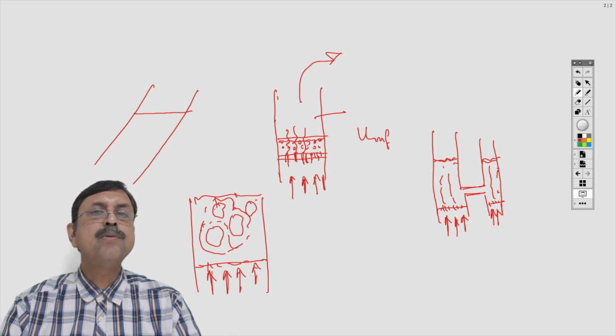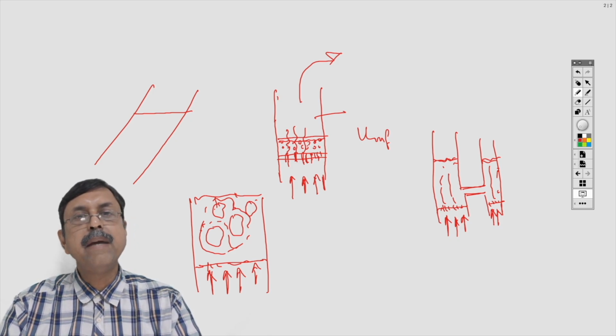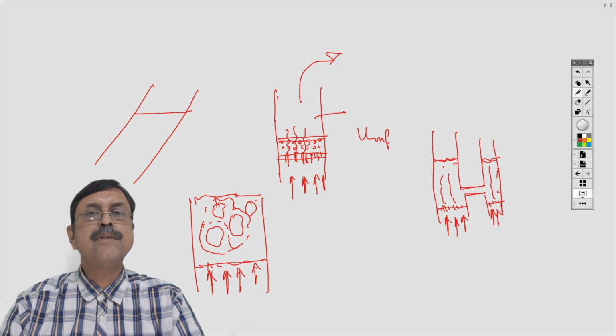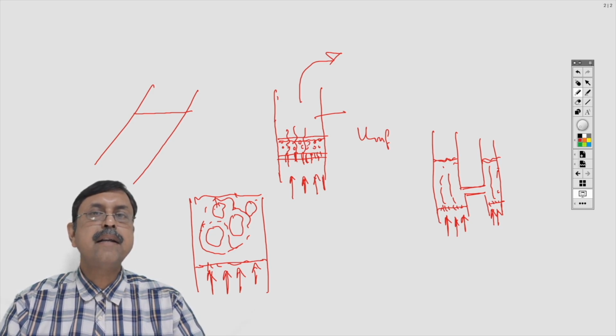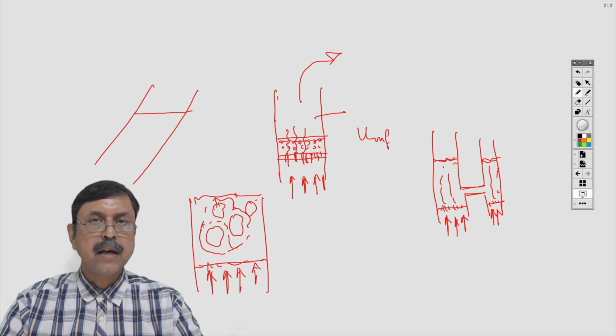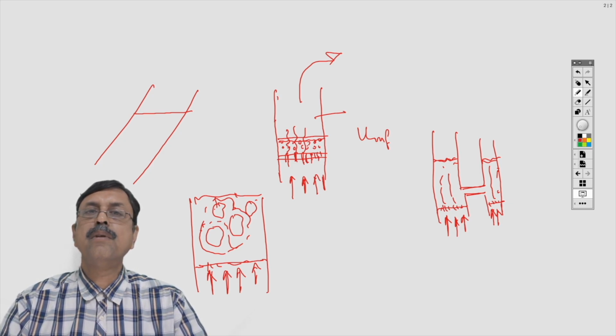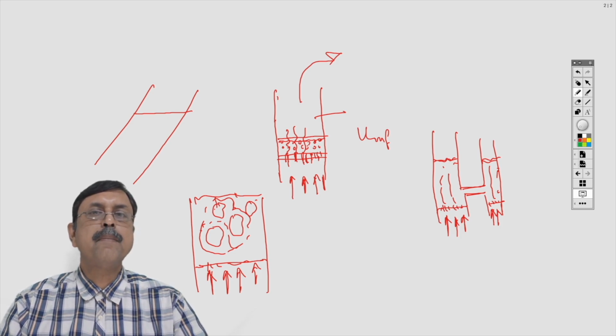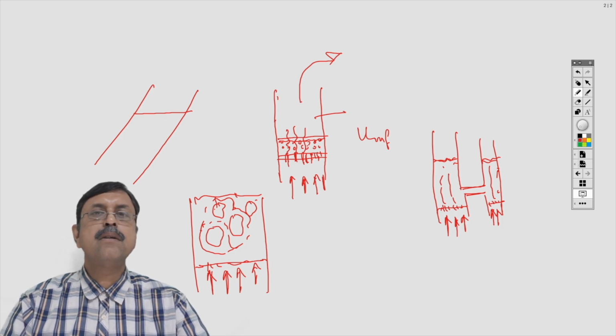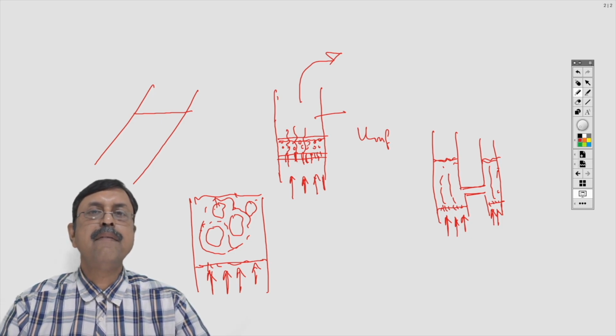Or if you have to absorb some material onto the surface of the particles, then also this fluidization will be very effective. Or if there is some reaction that you need to occur on the particle surface, then also the fluidization will be very effective. So for any kind of surface-based operation, fluidization or a fluidized bed will be very, very effective.